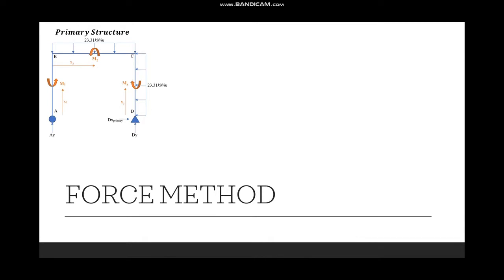So the first step in the force method is to conduct some equilibrium analysis by taking moments at 3 different points relative to a displacement from each joint, x1, x2, and x3. And we can form equations through this using equilibrium, and we came up with these, which will give us the moment at any point along that member. And knowing that m1 will be equal to 0 since there is no horizontal forces acting on this beam.